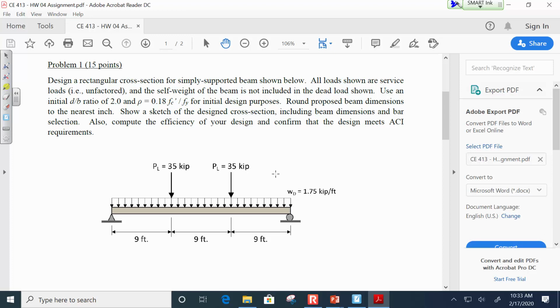So don't do that. Treat your dead load moment and your live load moment separately, and then factor them. Because I'm going to tell you, it's not WL squared over 8 for the dead load and the live load for either one of these 2 problems on the homework. Does that make sense?